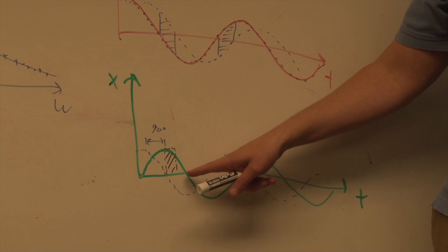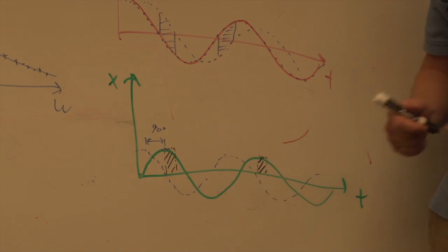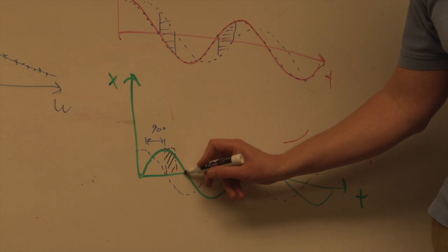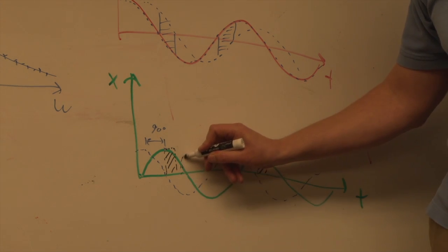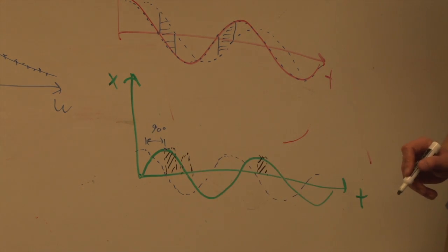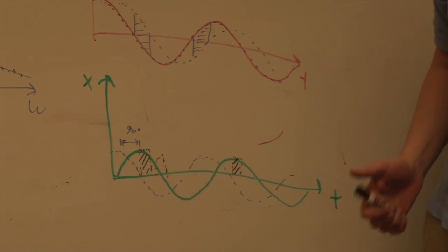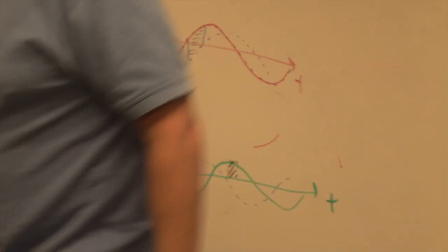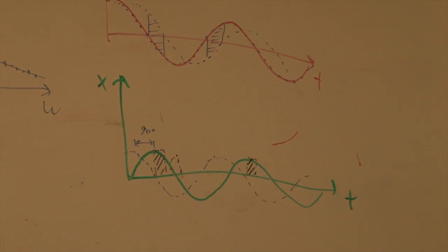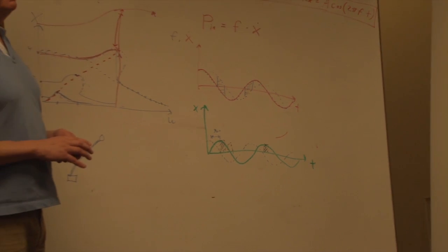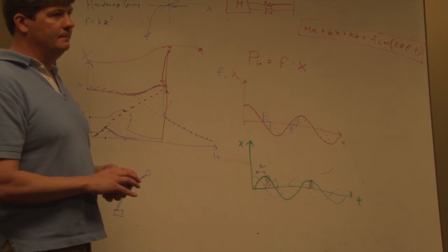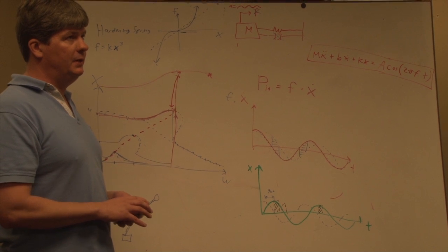If you can produce forces better at high speed, like perhaps your electric motor, then you might want to drive here. So it depends on your actuation system. You can choose all that based on your driver, as long as you're only pushing in the direction that it's already moving. As far as the resonant system is concerned, it's going to be maximally efficient. But it depends where your losses are.